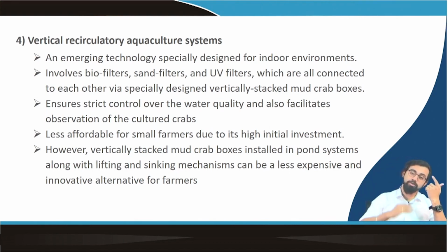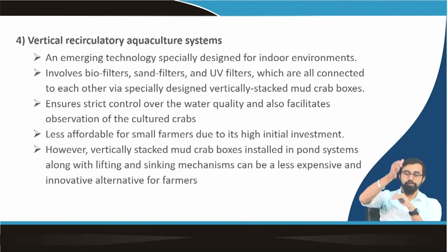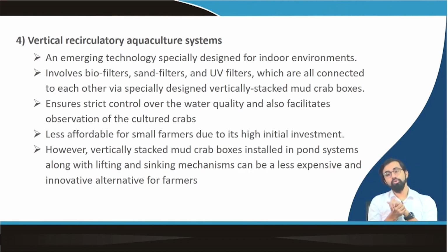Why is it called vertical? Because you can design it vertically with different filters at different stages. Once the water is utilized, you use a pump to send it to the reservoir, and from the reservoir through gravity it will go through the different filter systems, and it will again come back to the culture pond itself or the culture tank itself.